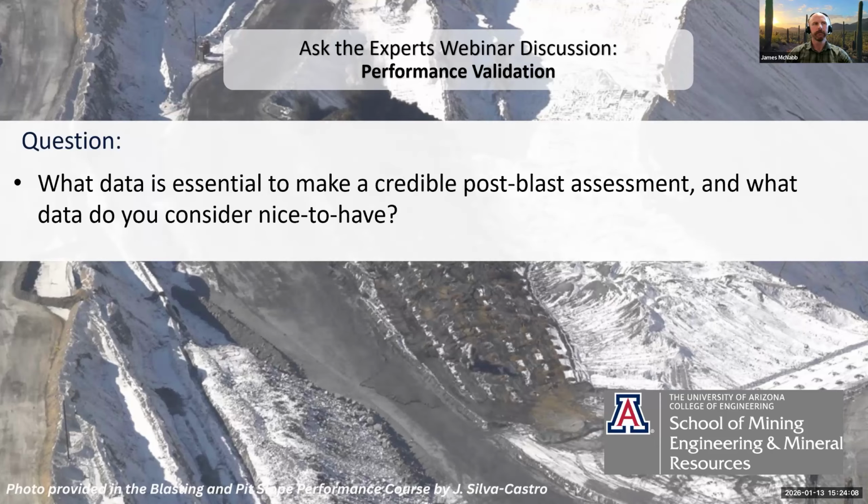Third, most mines now have video recordings, and video feedback from the blast is a great way to visually verify if your blast vibration levels are reasonable at the slope, because you can see the shock waves propagating and the direction of those shock waves.